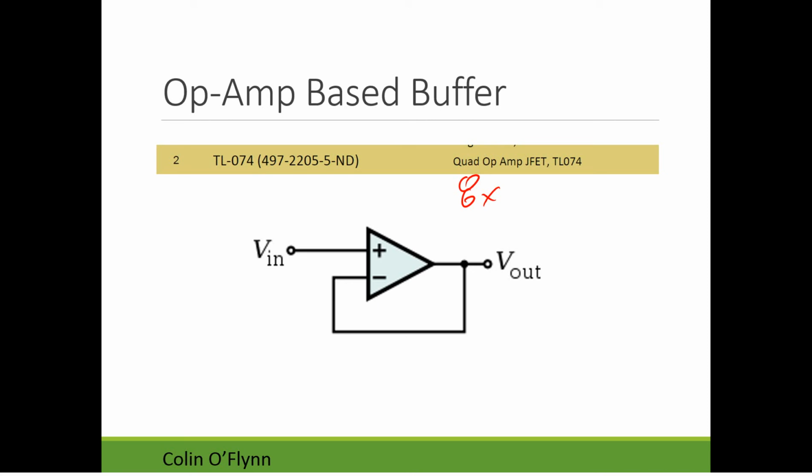The objective of the operational amplifier is that it controls Vout at the output. It is simply going to attempt, by controlling Vout, to make the difference voltage between these 2 terminals be 0.